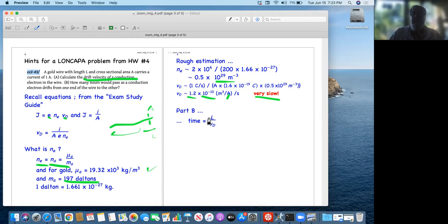That's because the electrons start moving in the filament as soon as there's an electric field. Now, the electron travels slowly, but the electric field travels at the speed of light. So the electric field will appear in the filament more or less the instant that you flip the switch. And as soon as there's an electric field, there'll be a current, because J is sigma E. So although individual electrons are moving slowly on the average, the current will appear almost instantly.